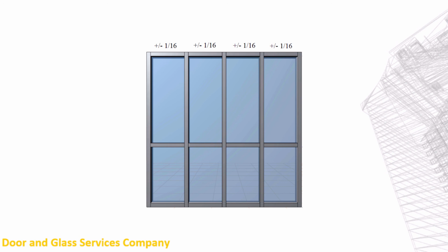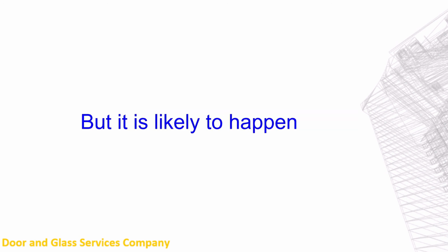If the frame has 4 panels, the size of its width could be as much as 3/64 plus a 16th, a 16th, a 16th, and a 16th, or 3/64 plus a quarter, different from the intended size. This result may be extreme, but all 5 errors accumulate 6.25% of the time, a little bit more than 1 in 20.